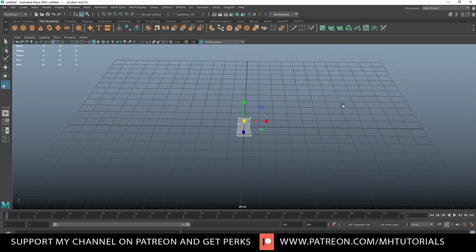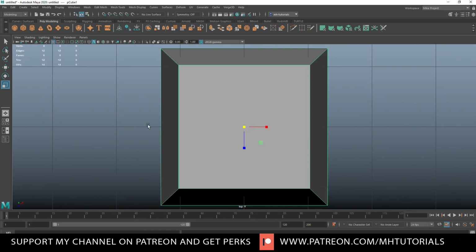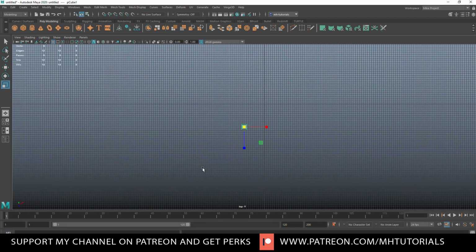So we have that. What we're going to do is right click in object mode, hit W, hold down X, and let's see, I think we're just going to use it on the corners here. If we're going to use the grid as a reference, this guy needs to be much bigger. So let's do that, and then jump to our top view, F to frame, and that's right.